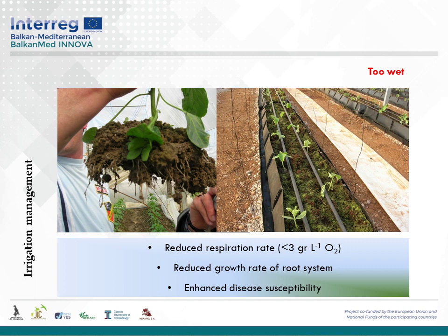Then the excessive water doses and very frequent irrigation sequences, or higher amounts of irrigated water, even when soil mulching is used, and things in general which do not consider either the right evapotranspiration needs of the plants, or the permeability of the soil to allow the excess of water to be drained out from the root system.